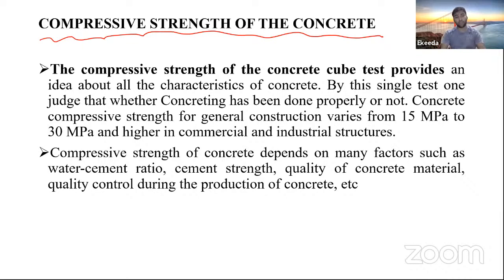Now in this test, we prepare a cube of size 15 centimeter into 15 centimeter into 15 centimeter. Is it or not? After preparing that cube we will place it in the water tank for curing purpose.